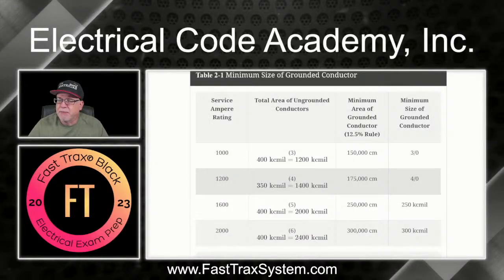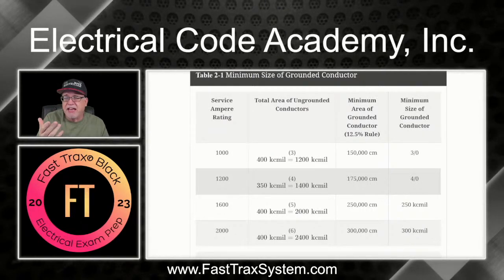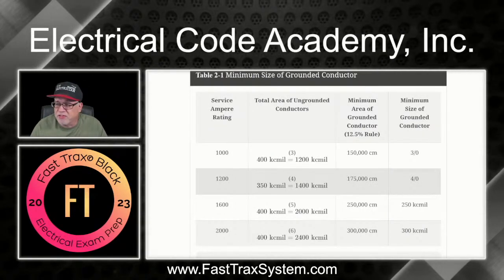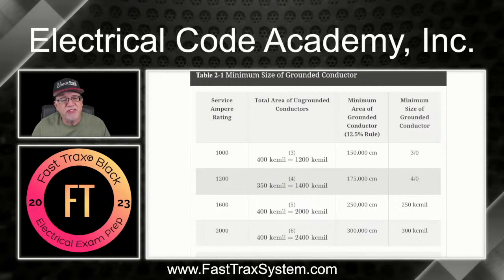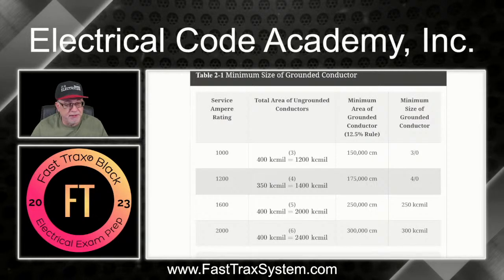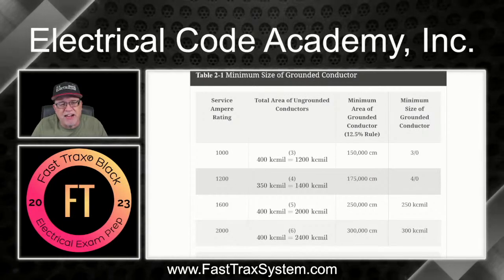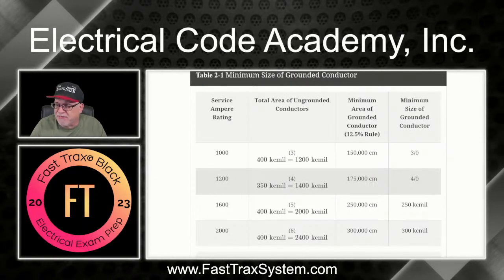And if I decided, because I want to go with smaller conductors for that same, maybe now I want to get a 1,200 amp service, or maybe I want to run 4 sets of 350 kcmil. Well, 350 times 4 is 1,400,000 circular mils, or 1,400 kcmil. And you just simply take that and multiply that by 12.5%, and that's where you get the 175,000.